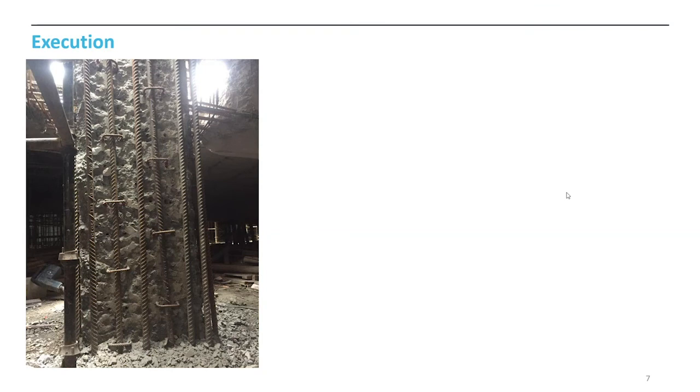What about the floor slab? Since there was no additional load on the floor slab, we checked it, but strengthening was not required. Is it the same grade of concrete poured on the slab and the columns, or are they different grades? No, they were different grades. If 40 grade concrete was there for columns, probably it was 30 grade for the slab.